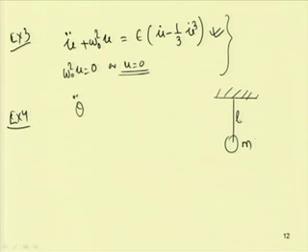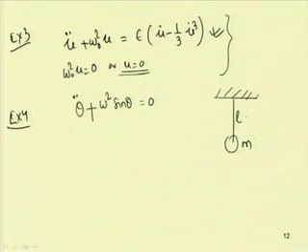So, the equation of motion can be written as, if it is moving with angle theta, theta double dot plus omega square sin theta equal to 0, where omega square equal to g by L. Here g is acceleration due to gravity and L is the length of the simple pendulum. If one does this qualitative analysis, here one can find f theta,